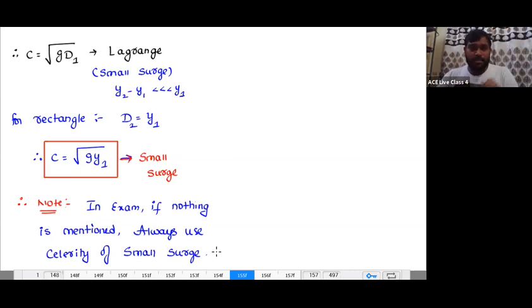increases by this percentage. Due to sudden rise of the or sudden lift of the gate, the water level increases by this percentage. If they mention the difference between Y1 and Y2, my dear, then you must have to use that. But if they don't mention that, then you always go with the small surge. If they don't mention whether it is small or large, you always go with the small surge.